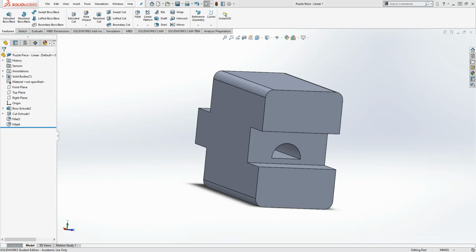So I pick the corner here, use the fillet tool, right, and it'll fillet edges. This is a little bit crazy right here, but basically it takes and rounds out those corners. So I can hit Control-Z, and we can try that again. Maybe make it a little smaller. Right in here, the radius of curvature is 10 millimeters. That's a lot, so I'll maybe do something like 2 millimeters.